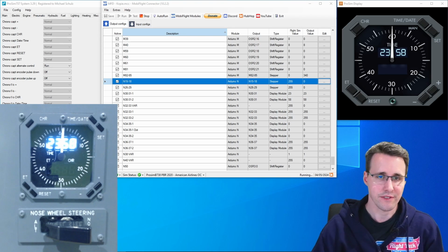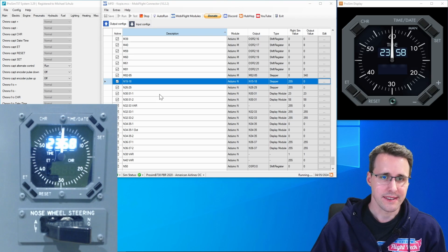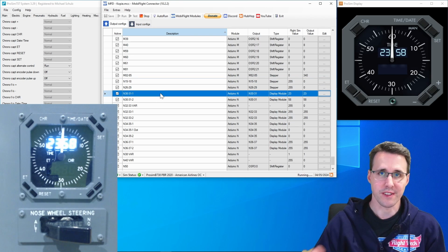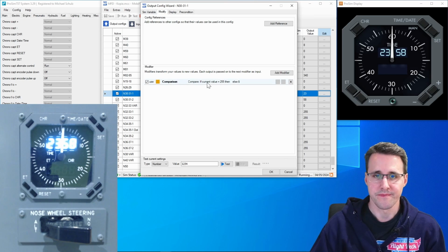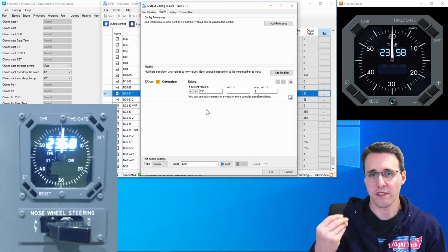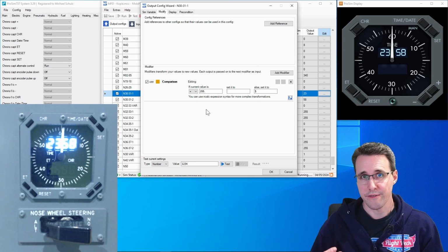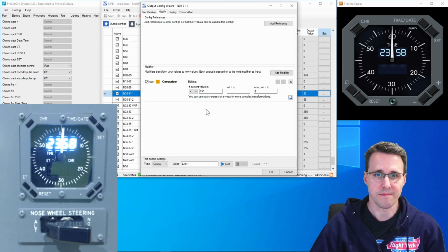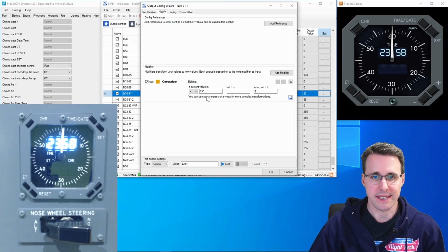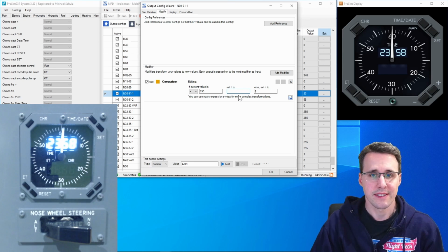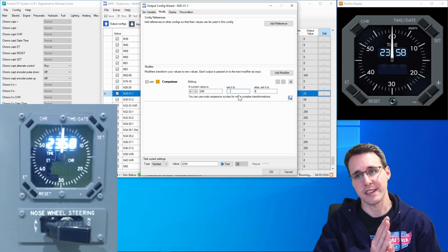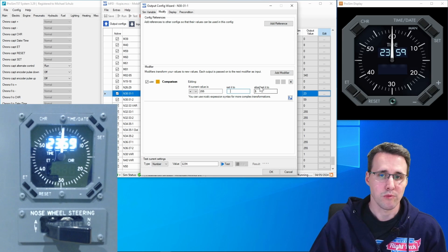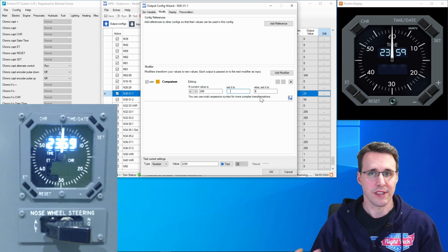This was something I haven't shown you. When we go back now to the configuration for this upper display, there I have made a comparison in the Modify tab. So this blinking on and off, you remember, an off value gives us a -1 from Prosim, which is 255 in my case. So if the value is 255, then set it to 2 spaces. So I have inverted here space 2 times so that I shift out the numbers. Otherwise, give it the value that comes.